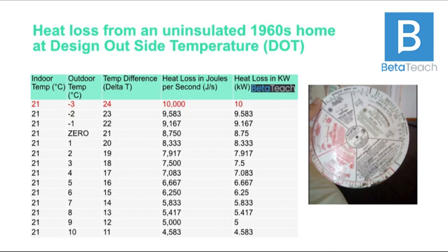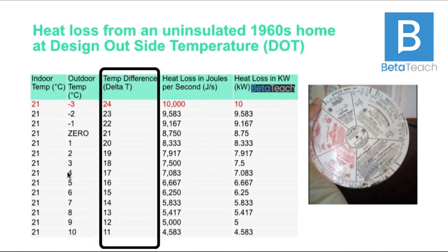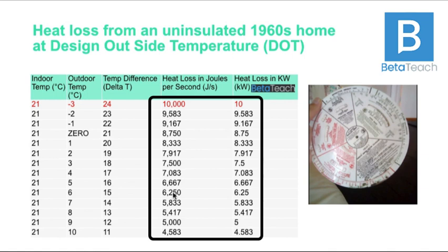So we just tend to put these things in, and heat loss calculations sort of started to not be used or become so popular, and obviously now with heat pumps we need to be sizing the home. So again, don't get too bogged down with the numbers here. We've got the indoor temp, and again here we've got the outside temp. So that's always changing. The outside temp's always changing, which means the difference between these two temperatures is always changing, which means our heat loss is always changing.